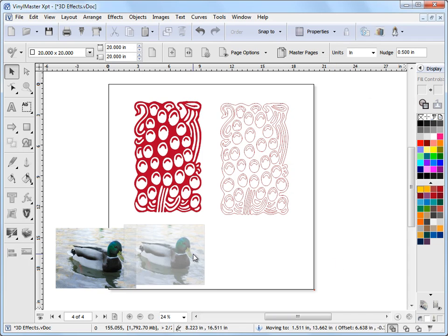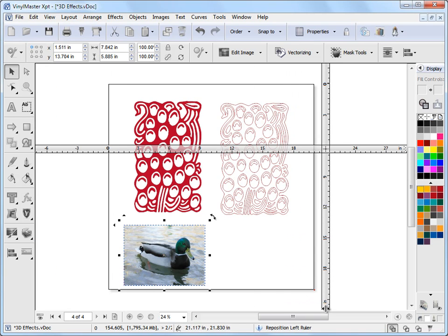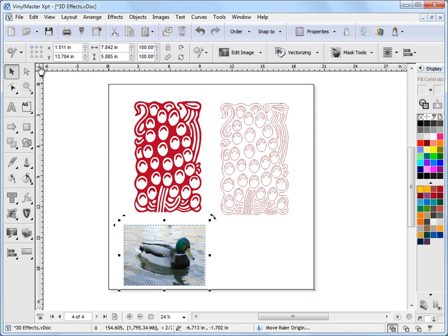Now when it comes to the rulers, you'll be pleased to know you can actually move these around like this. So I can put my rulers wherever I like. Okay, so that shows you how to do that. And I can also reset my origin point. So I can set my origin for my ruler wherever I want it. If I want it down the bottom corner here, you can see it snaps to the page. I can put it down there and work from that position. So 0, 0 is from the bottom left corner. If I prefer to have it in the top left corner rather than the bottom left corner, I can just put it up there. And as you can see, it just snaps to the page, like so. So I've got my 0, 0 ruler there. So that's how that works.